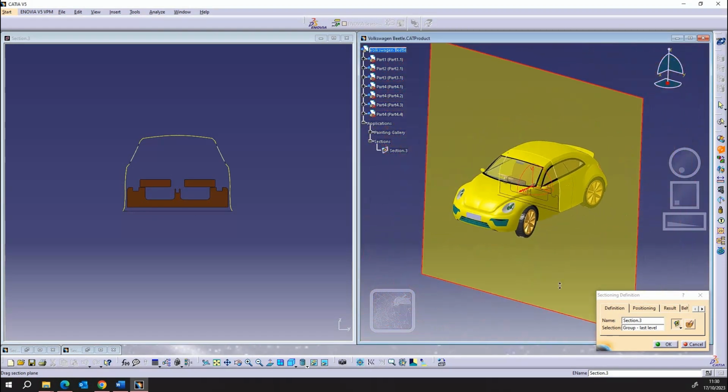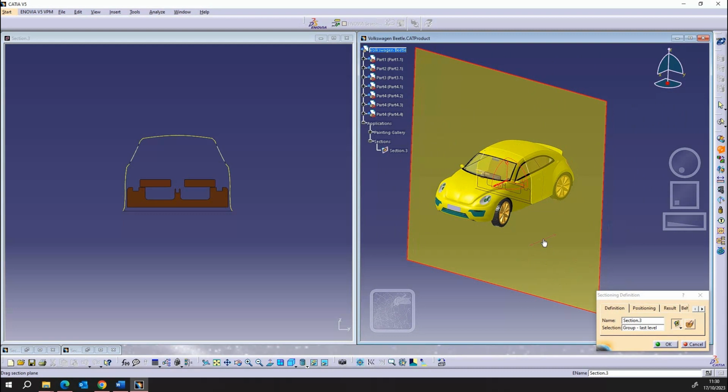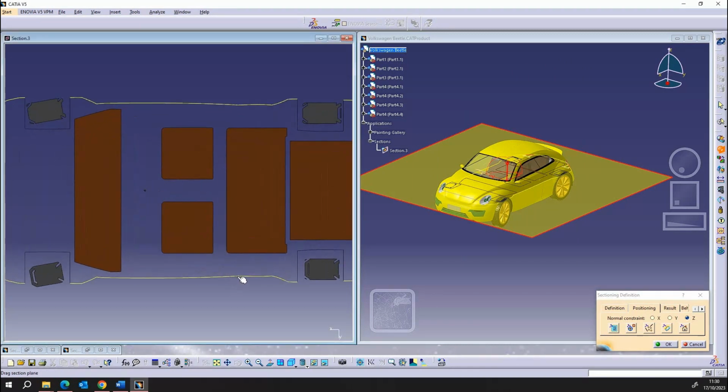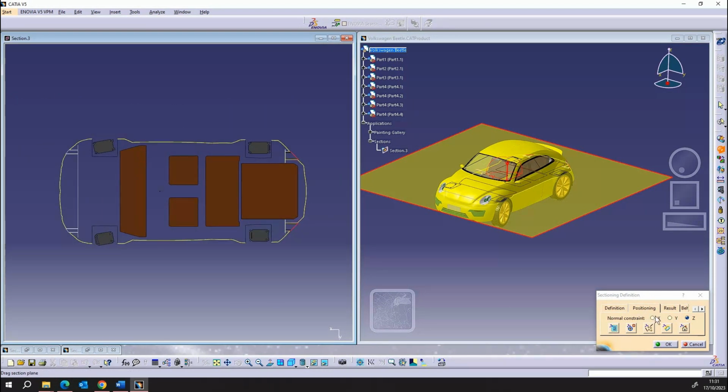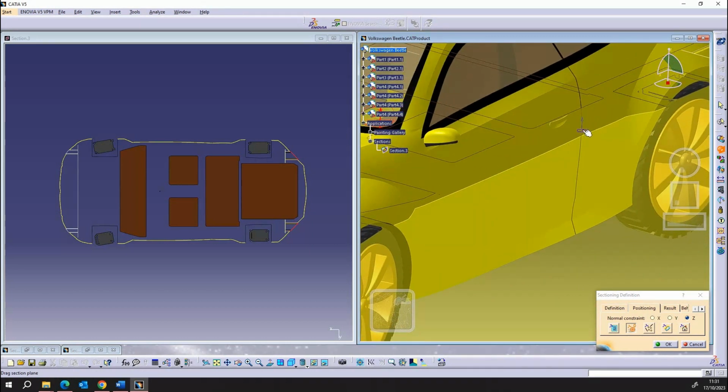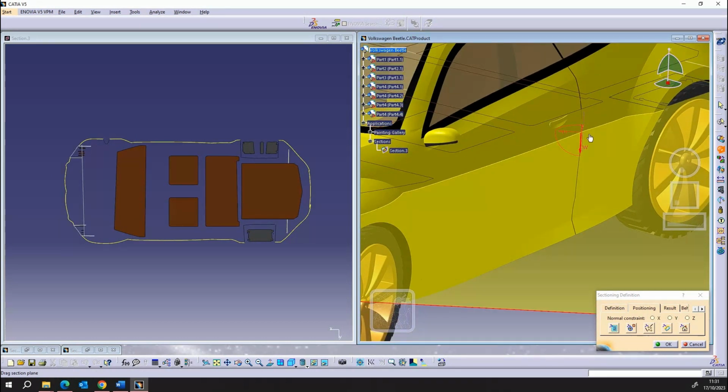Alright, we can reduce the size of this, and now because we want to measure the tolerance between the door panel and this, it's best if we take our positioning from the z-axis. As it is here, you see it clearly, which means if you zoom in, you can see the discontinuity right here, which is the clearance between the door panel and the rear panel. Now that we have that, you can choose different methods. You can set the geometrical target, which means you can easily just do this as well. It gives you the same thing anyway.